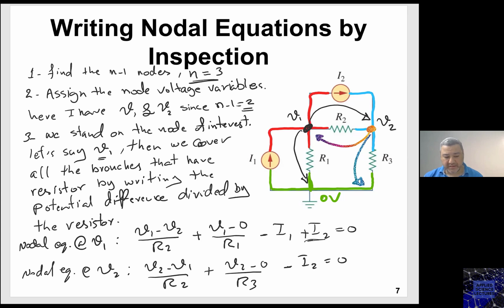Sir? Yes. So basically, you draw your nodes, declare each node equal to a voltage. You write the KCL for each node, for example.